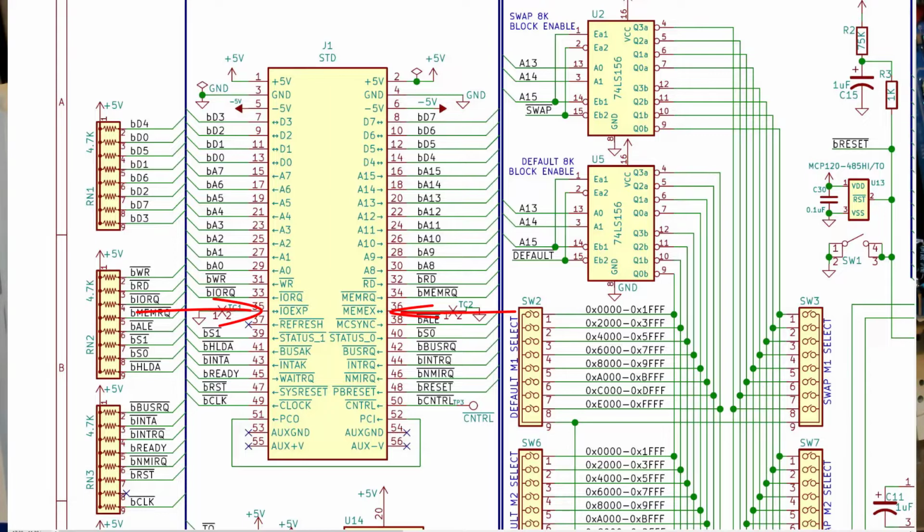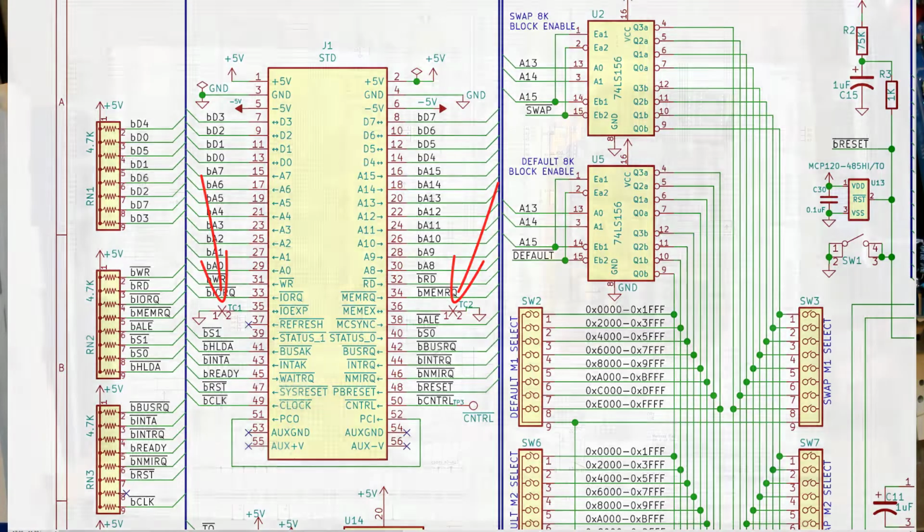On this version of the card, we're not going to control or qualify these signals for any decoding. If somebody finds a use for them, they're both active low. They're on this card tied low using a cuttable trace to ground. So you can come back, you can cut the trace, you can use them for whatever application that you find. And if you find a good application, then maybe the next version of the card will include a use for them.